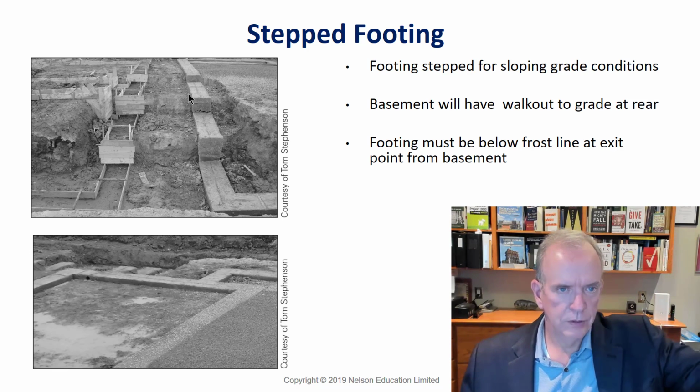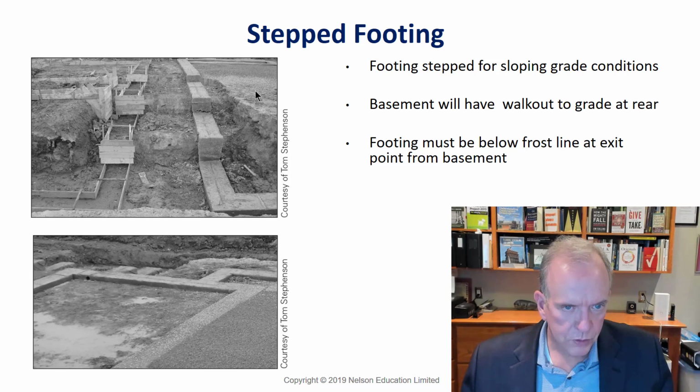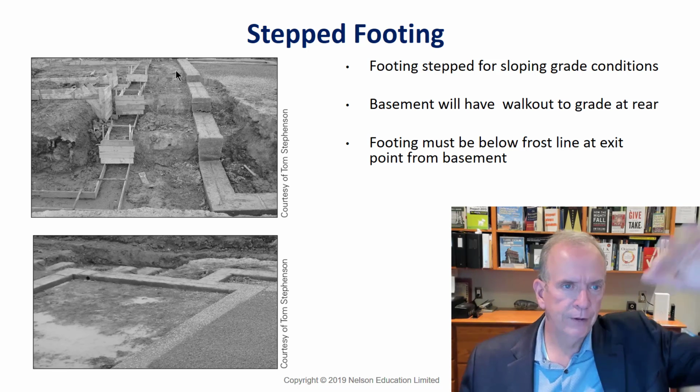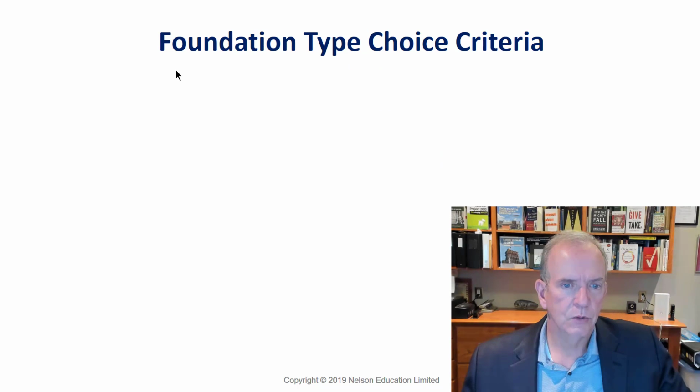Basement walkouts. You ever see a basement walkout? Because what's going to happen here, in this case, there's going to be a floor slab going where my arrow is, and the grade is going to be much higher. So where the ground finishes will be 4 feet above where the bottom of this footing is. That will allow the basement walkout from that point. And then, of course, it's going to slope up and be filled in between the houses as it goes up the hill.